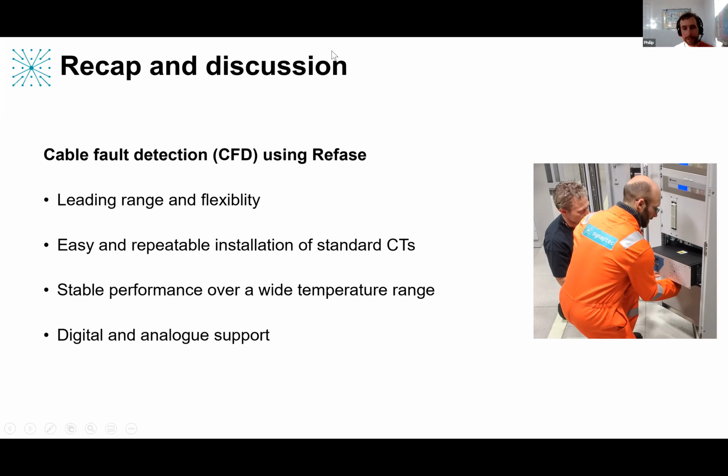Now that's very high performance and a great technique for those situations where the fiber is embedded next to the conductor. In many distribution applications, if there's fiber that's in a duct nearby, which is not a problem for installation of electrical sensors, it means that you can't use OTDR to do accurate fault location in that way. Hopefully that kind of answers that question. But it's certainly a very good technique for when you're offshore.